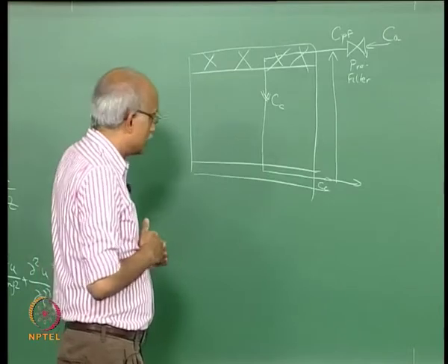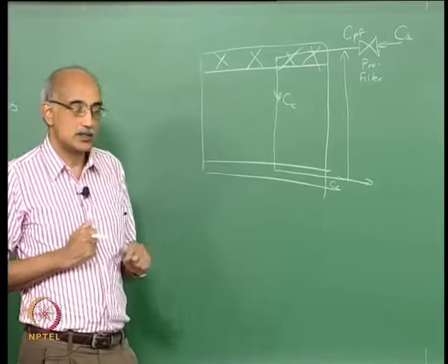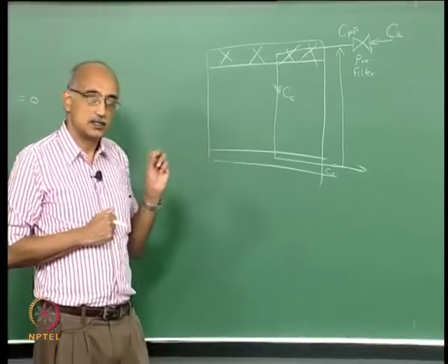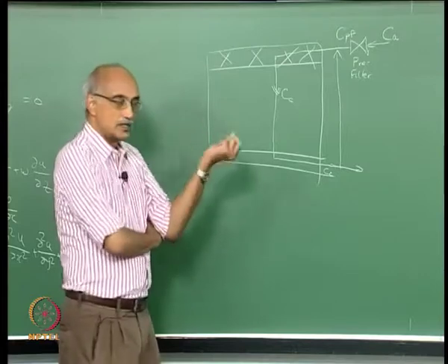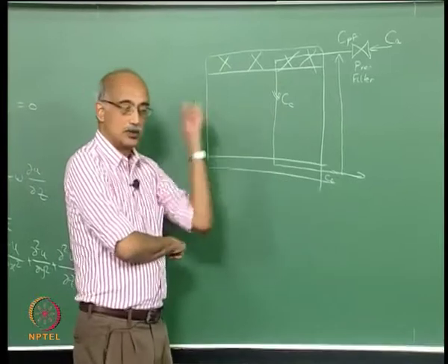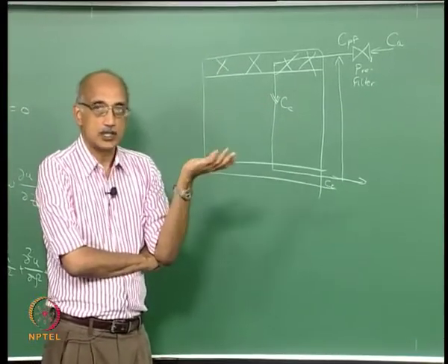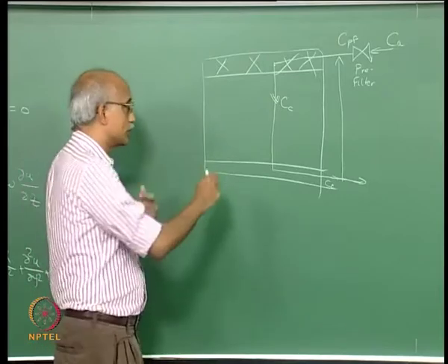Now the other concentration that we have to be aware of, I mean, what are we missing here? Is this a full picture, or is there a term that we are missing? Just think about particles. What is the basic assumption here? The basic assumption is all the particles are only coming from outside, but we know that's not true because particles are also getting generated inside the clean room. So you need a source term.